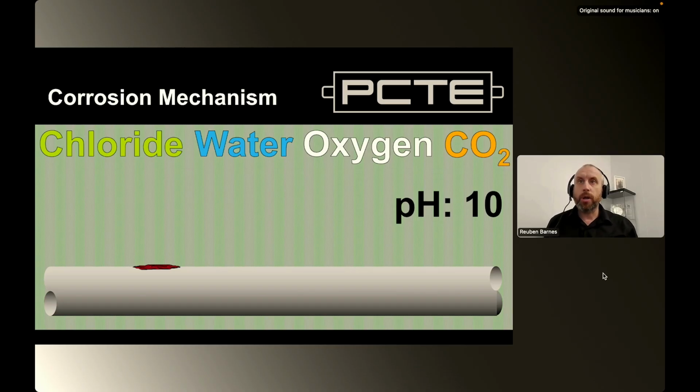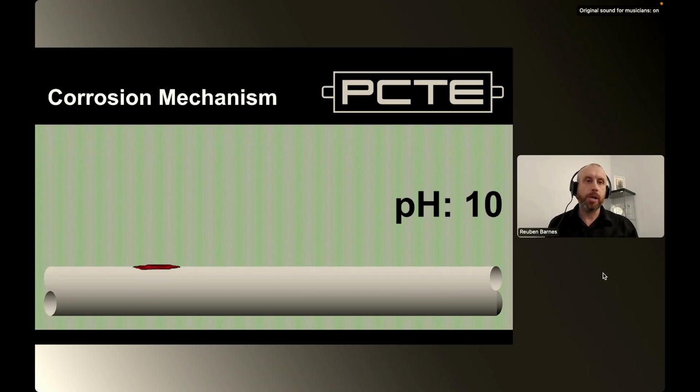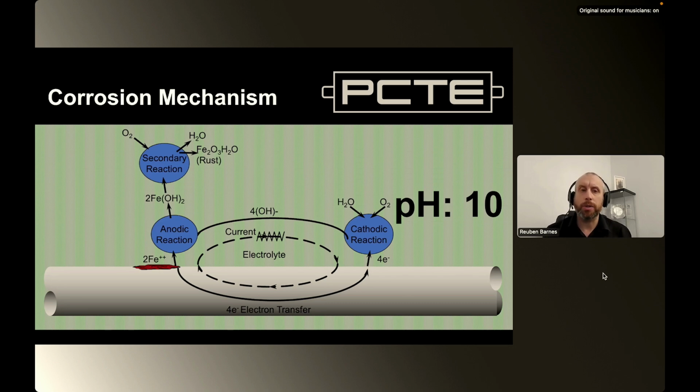Obviously, once corrosion occurs, we can look at the chemistry behind exactly what's occurring. For those of you that have studied redox chemistry, you'll understand that we generally have an anodic and a cathodic region, one providing the electrons for the other. The corrosion occurs at our anodic region, where the iron is reacting with the oxygen being provided, creating ferrous oxide, which we know as rust.